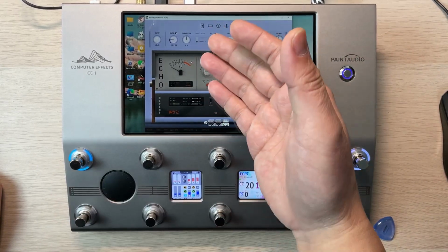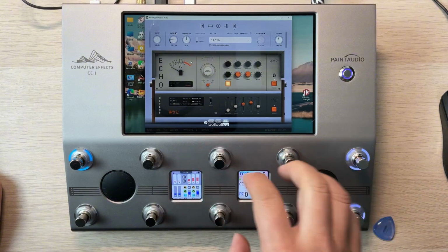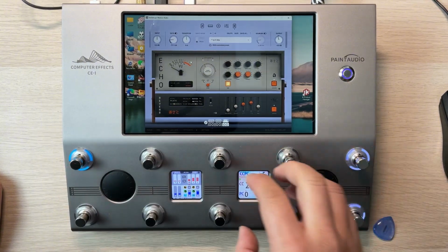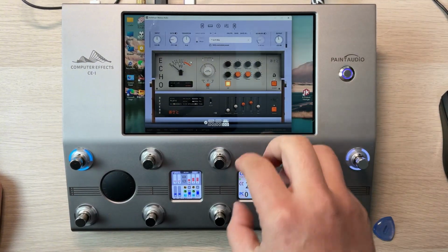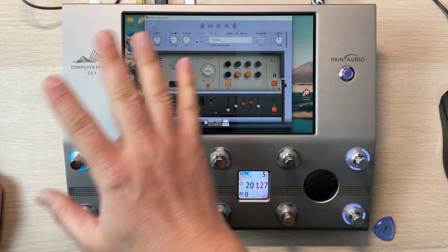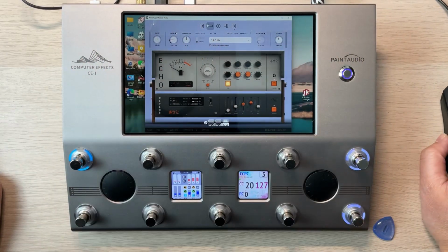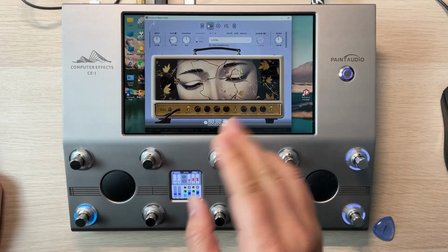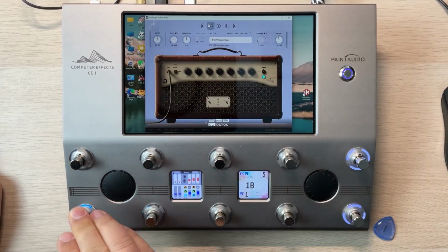This CC toggling can actually be achieved by our MIDI Captain as well. With the MIDI controller, you can go to the USB setup mode and set the CC commands to auto toggle the value from 0 to 127. So we have several ways to achieve this. And we can see now 1, 2.